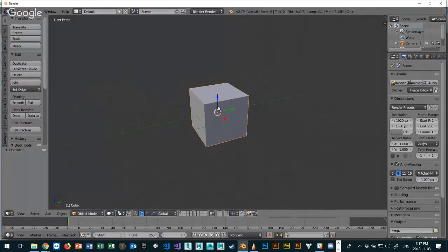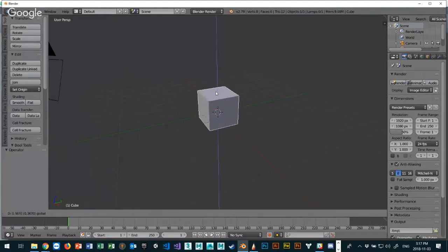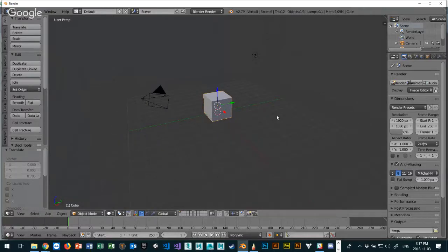All right, so I know how to zoom in and out. I know how to move the object in three-dimensional space. Pretty simple. How about orbiting? I want to orbit around this object. If I click the middle mouse wheel and drag it around, I can orbit around an object by middle clicking the mouse wheel and dragging. Okay, I'm orbiting around an object. Are we good with this part? So again, zooming in and orbiting. Those are two ways we can survey the scene.